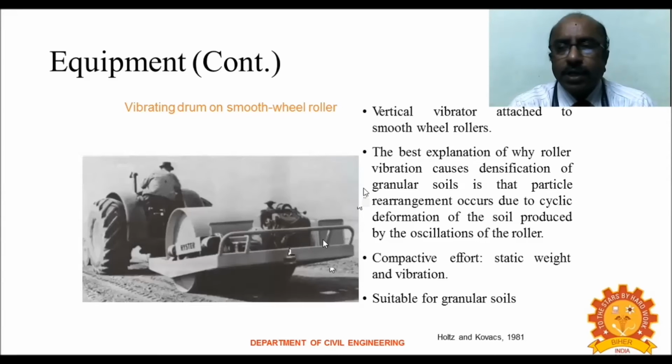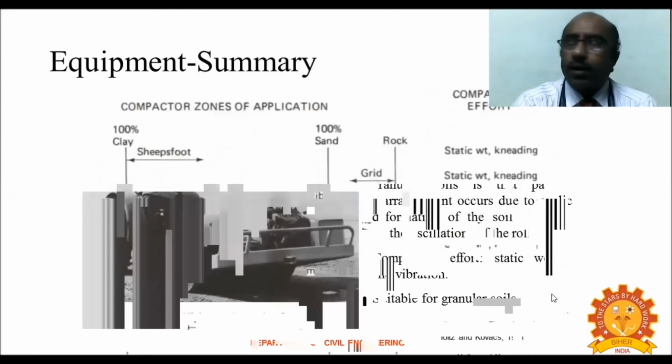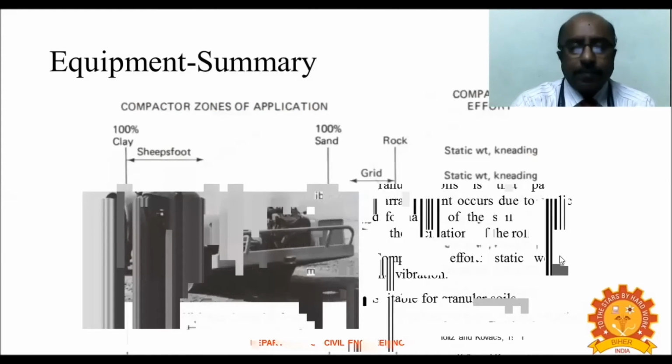The best explanation of why roller vibration causes densification is that particle rearrangement occurs due to cyclic deformation of the soil produced by oscillation of the roller. So these are suitable for granular soil, particularly coarse sand or gravel.